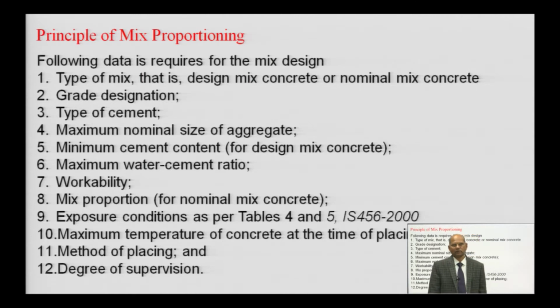If it is a nominal mix concrete, we do not have to go for a rigorous design, but by just taking some nominal percentages of cement, coarse aggregate, fine aggregate, water, we can achieve a certain grade, but that grade is permissible only up to M20 grade of concrete, not higher than that.